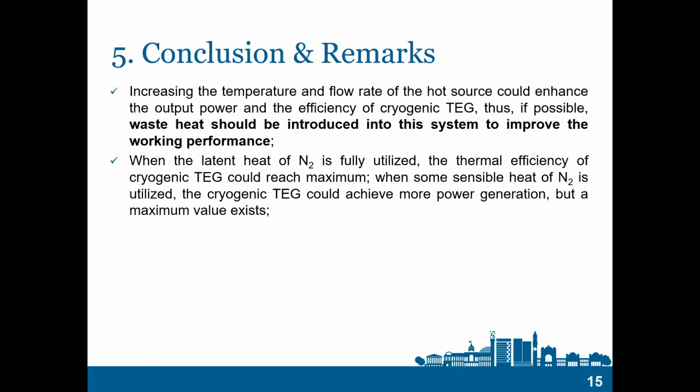Second, when the latent heat part of the nitrogen is fully utilized, the thermal efficiency of the cryogenic TEG could reach its maximum. When some sensible heat of the nitrogen is utilized, the cryogenic TEG heat exchanger could achieve more power generation, but a maximum value still exists.